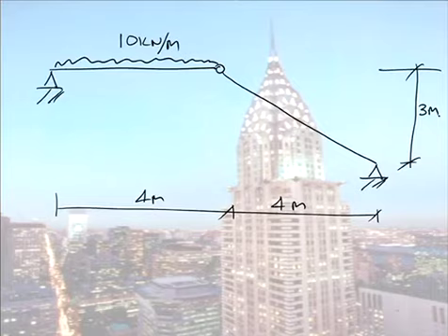When it comes to a cantilever, particularly, people do that and they go up, I go down, and I go across. So then they go a positive shear, positive down, so then they go to the moment diagonal like that because they think it starts at zero. When in fact you have to actually start this one up because you have this moment here.